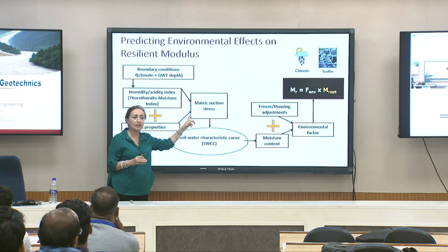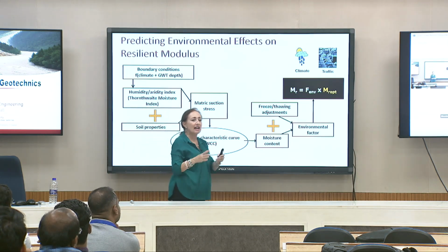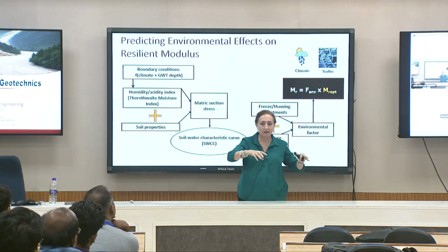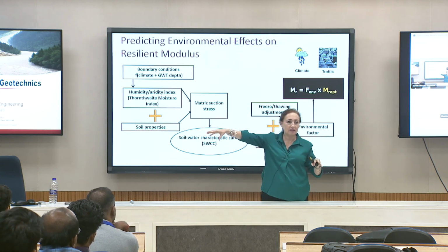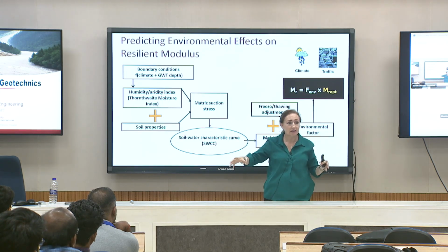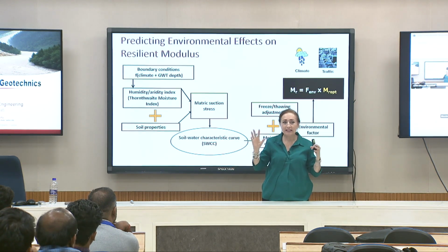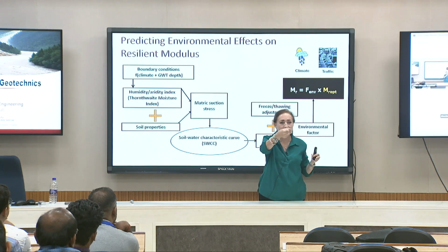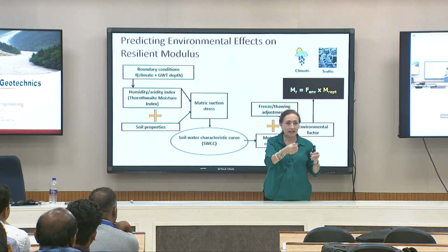What I'm telling you is you're going to have exactly the same soil here and in the desert in the Sahara, and the suction at equilibrium of the two soils will be different, because of the environmental conditions that you have. The soil can have exactly the same pore size, the same pore network, the same capillary.